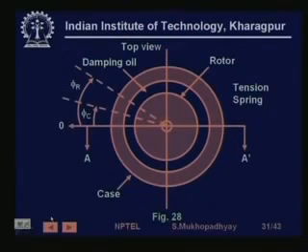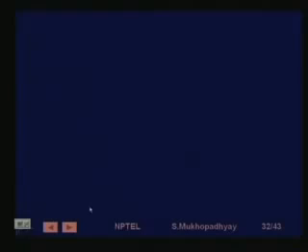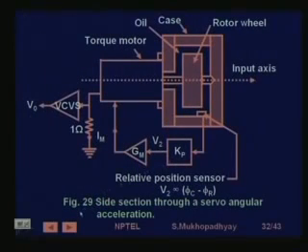Anyway, again we have this rotor which has some moment of inertia, which is the rotational equivalent of mass. We have damping oil which gives you friction, and similarly we have some torsional springs. So you again effectively have a mass spring damper system, but now in rotational terms. So you can have both. We'll skip this slide. This is what is known as a closed loop measurement method.